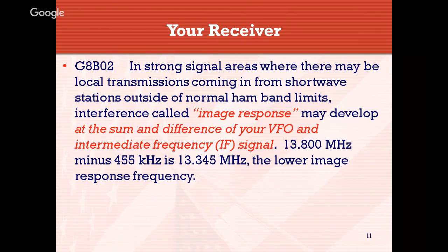Now, that sounds kind of odd, I know, but even the receiver in your car can cause some issues, and there is a little bit of a transmission outside of that because of how it mixes internally. You still have the possibility of an actual RF signal emanating from your receiver. And this is what was happening to our repeater on the UHF frequency link. So we decided to re-coordinate that UHF frequency. And once we put it on a different UHF frequency, the problem went away.